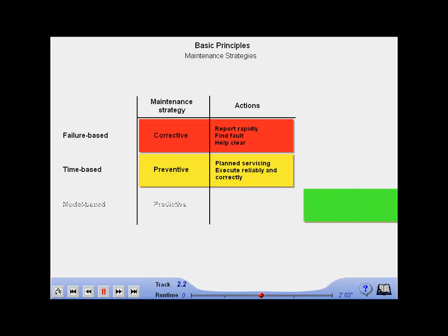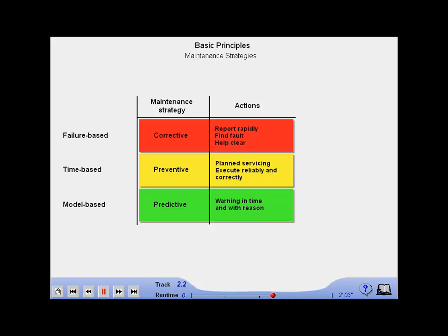The predictive case is based on a status model. This means that optimally the operator receives a clear and explanatory warning in good time that a fault might occur in a unit or system in the near future, or an indication is given of the remaining expected service life of the equipment. This means that practically all additional costs are eliminated. This case requires extensive knowledge of the process, because to ensure a meaningful prediction, often very many statuses and characteristic values have to be evaluated.